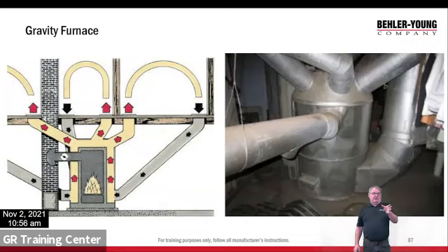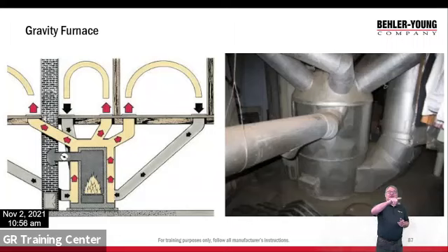And you can see the yellow pipes. The yellow is the space between the jacket and the metal, basically a wood stove inside it. It was usually cast iron, so you'd heat up that metal inside. The air would pass around the outside and pick the heat up. By gravity, it would pass into the rooms. You can see the ductwork's always going on a diagonal upward. Then the cold air would, by gravity, come back down that return, back into the furnace.